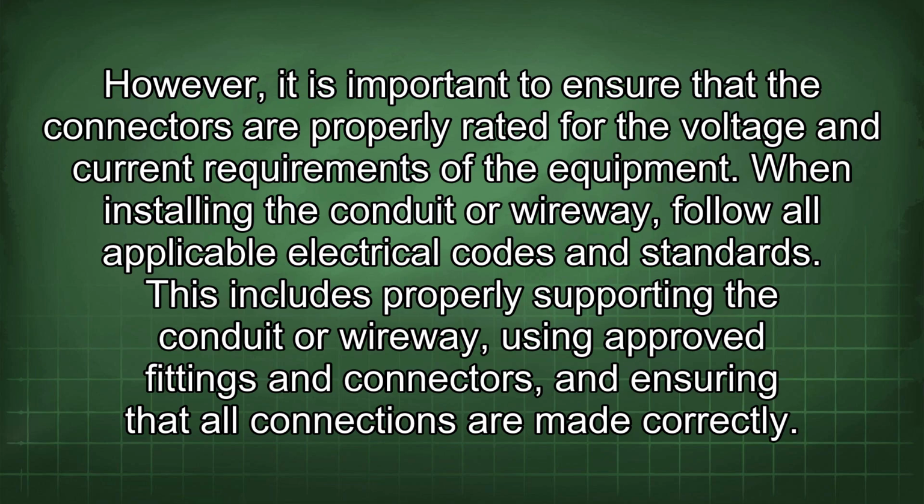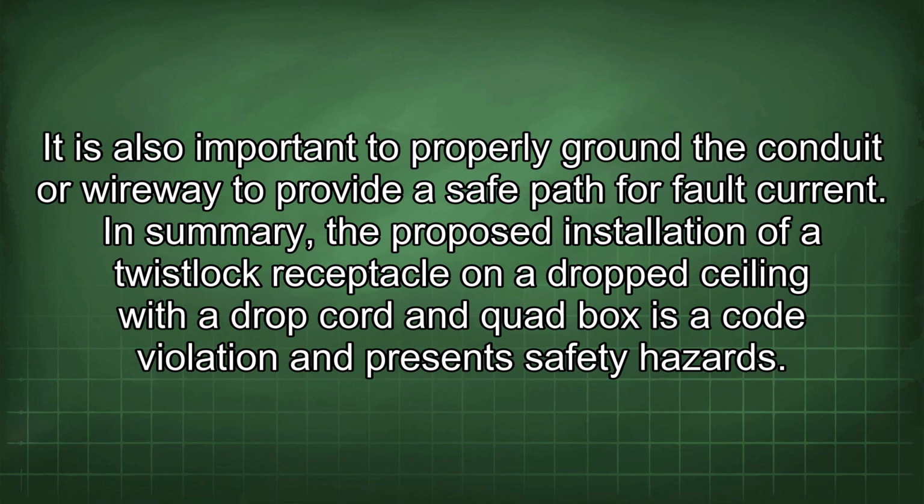This includes properly supporting the conduit or wireway using approved fittings and connectors, and ensuring that all connections are made correctly. It is also important to properly ground the conduit or wireway to provide a safe path for fault current.